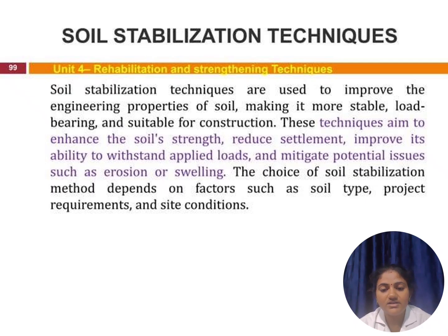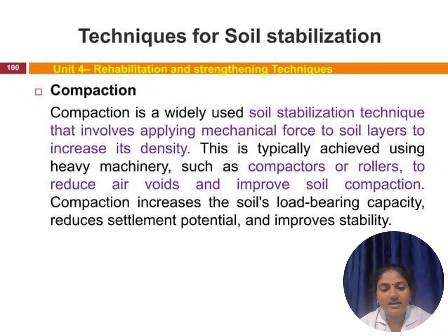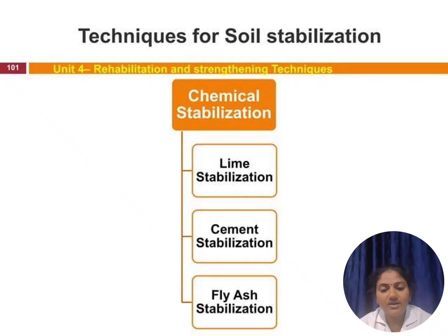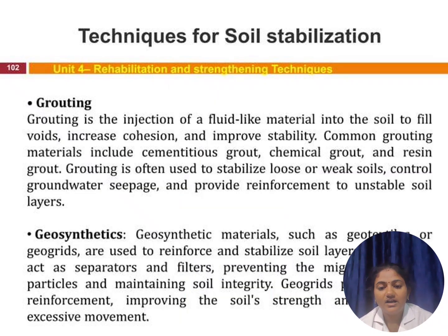And then soil stabilization, which enhances soil strength, reduces settlement, and improves its ability to withstand applied loads. Techniques are compaction and chemical stabilization, done by lime stabilization, cement stabilization, and fly ash stabilization. Here we can also apply grouting and geosynthetics.